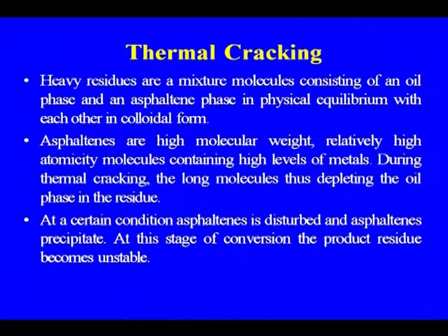Thermal cracking. Heavy residues are a mixture of molecules consisting of an oil phase and an asphaltene phase in physical equilibrium with each other in colloidal form. The asphaltenes are high molecular weight, relatively high atomicity molecules containing a high level of metals.